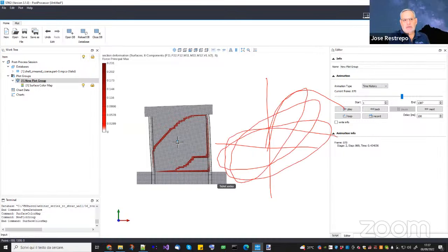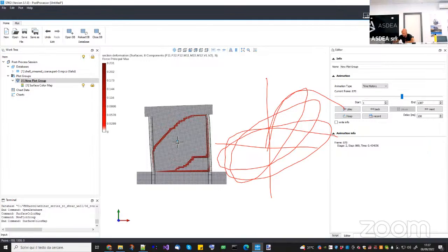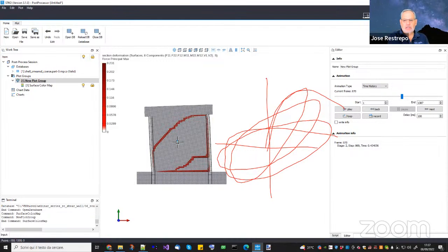That pinching is very typical of concrete. The shift that you showed initially is more like reinforcing steel as a material. When you experience that shift, but as a 1D relationship in concrete, you will have that pinching before the crack closes, you regain stiffness, and then you go and merge. Depending, some models will have some damage, and then you don't merge to the backbone curve, but you merge somewhere below. It just depends on what you want to do with your model. Maybe not that important, but the pinching, it is important.